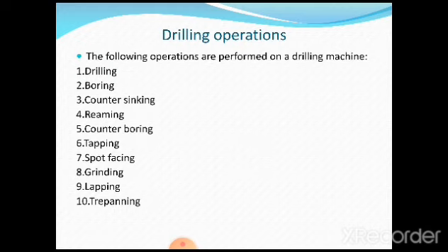The next one is a boring operation. Boring is nothing but enlarging the previously drilled hole. Generally the definition of drilling is the production of a hole which is limited to a certain diameter only. But if I want to go for larger holes, that is called a boring operation. Counter sinking, reaming, that is fine finishing of the hole.